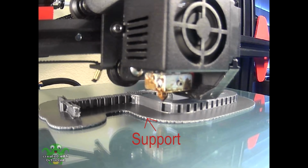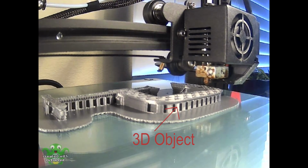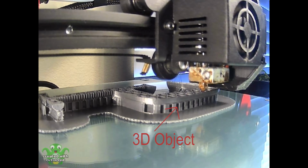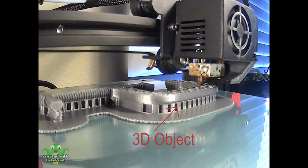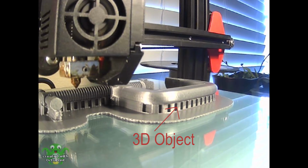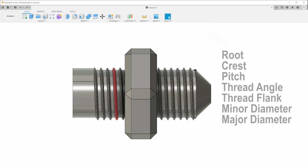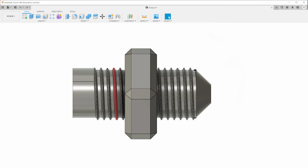Now, before we cover how to create a thread, I want to go over some basic terminology that will be helpful to know. It is not necessary to memorize these words, but they will pop up often, and being able to recognize them will give you a better understanding of making threads. The following is a diagram I made to illustrate the anatomy of a thread. The terms I will be going over are root, crest, pitch, thread angle, thread flank, minor diameter, and major diameter. To start off, the root is the gap between the crests.